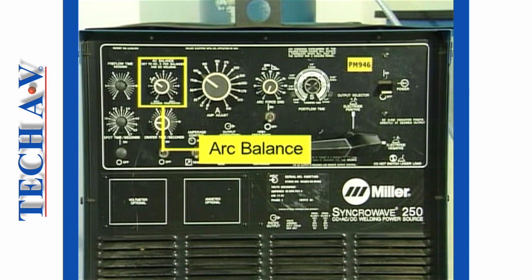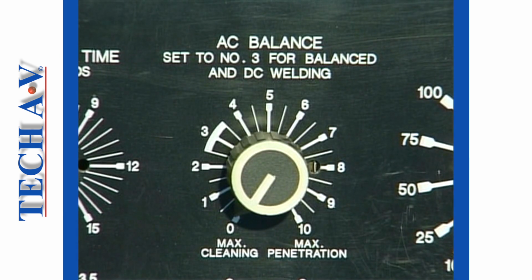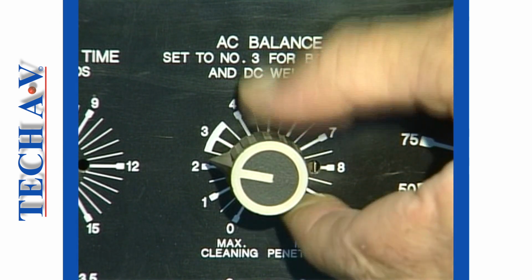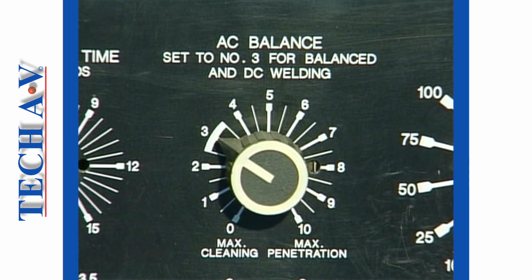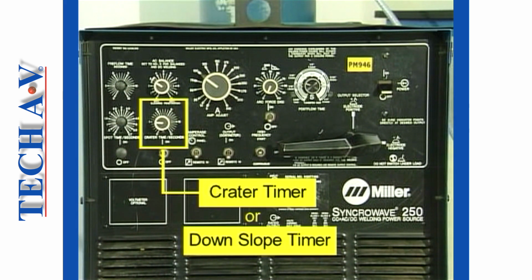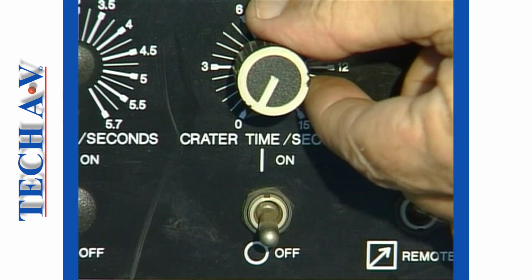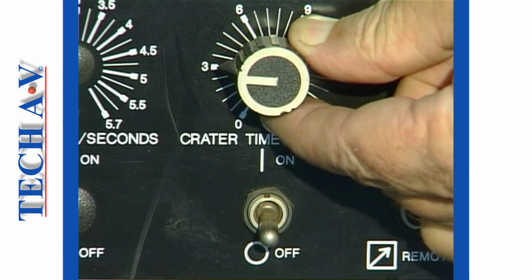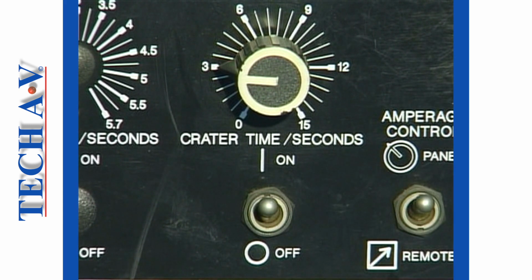The next control is for arc balance, which during this basic course we will not require. This controller should be left set in the position indicated. This controller is called a crater timer. The same control on other machines may be called the downslope timer. This control is used to gradually reduce the welding current when approaching the end of a run.